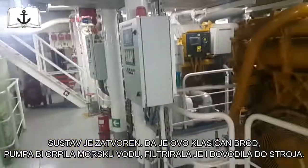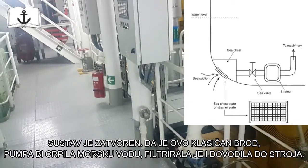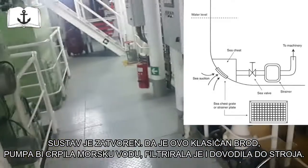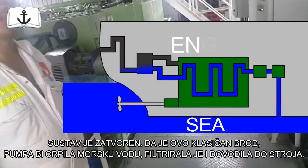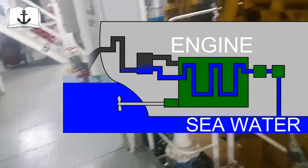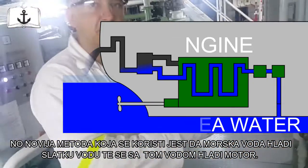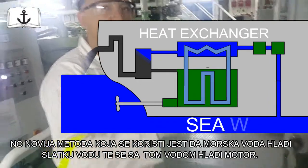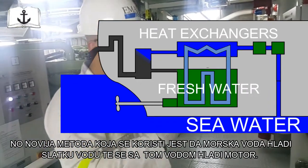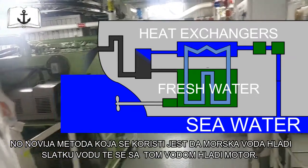Okay, if this was a conventional engine, where would this water be coming from? We get this water from the seawater. So you would get water from the sea chest, then the filters, and then it would be going through the engine. Not now, because the new engines have fresh water in the system. So first you're taking the water, then you have heat exchangers, and the seawater is exchanging the heat with the fresh water. Okay, this is another way of doing it.